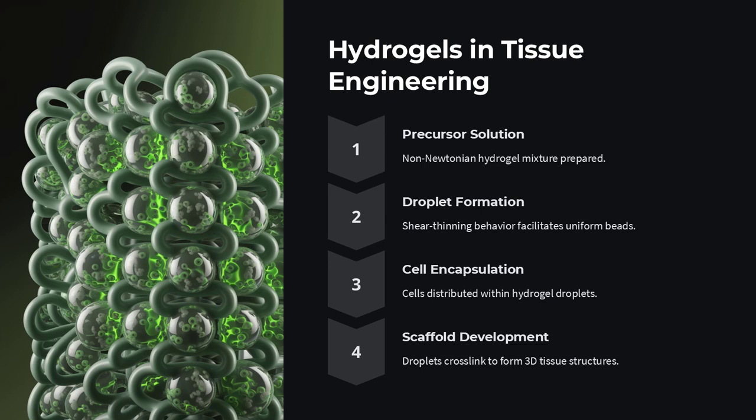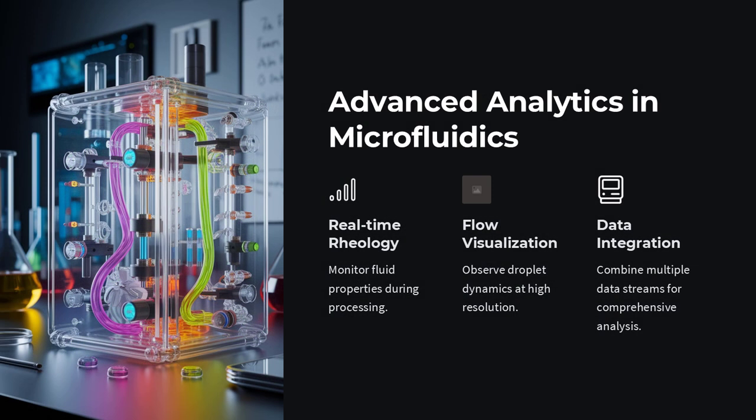Here, the careful adjustment of flow conditions and surfactant concentrations ensures that the droplets do not coalesce over time, preserving the product's consistency. The question then becomes, how can manufacturers ensure consistent droplet formation in large-scale production? The answer lies in scaling up microfluidic principles, using parallelized channels, real-time monitoring, and automated control systems to maintain the same delicate balance achieved in laboratory settings.